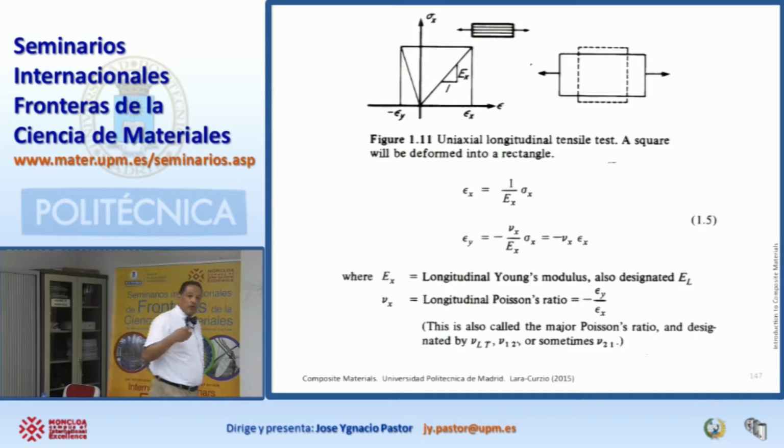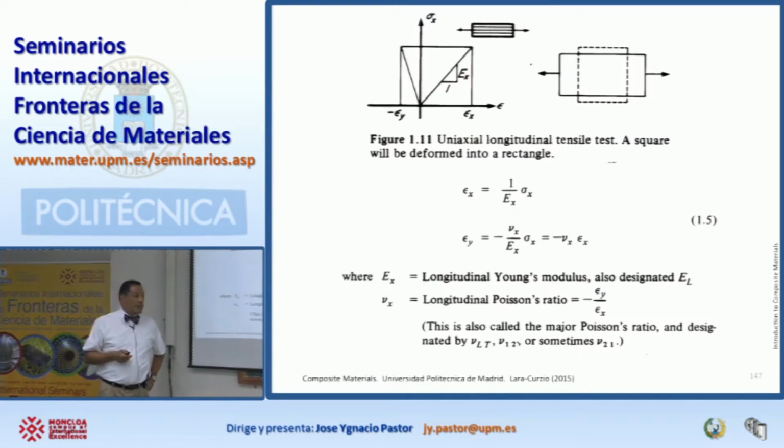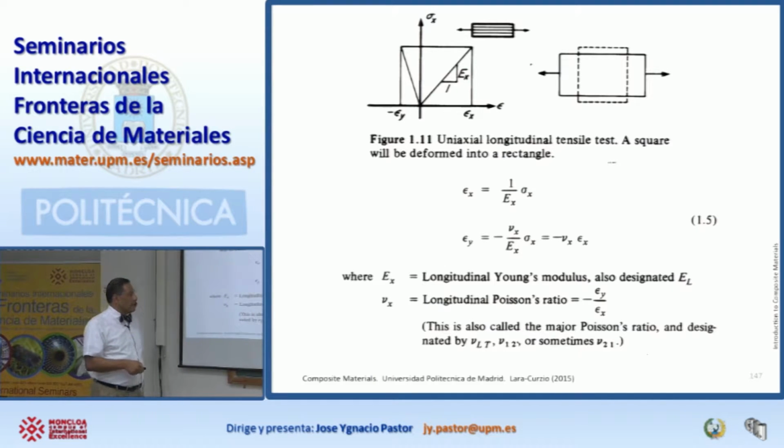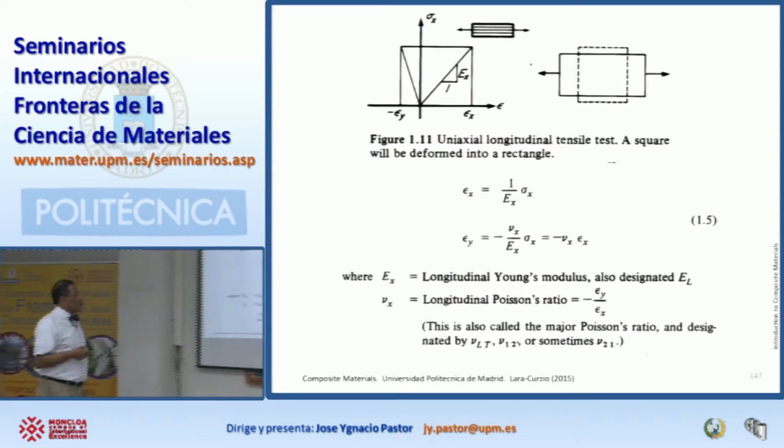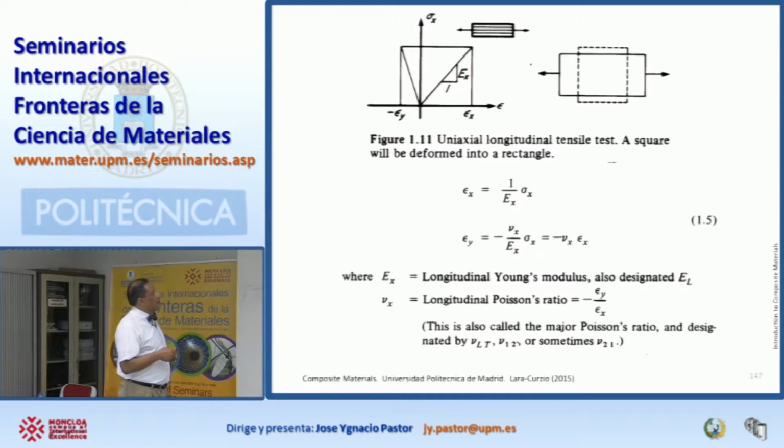Now, if you're an engineer working for Boeing, you are not going to use this type of data. You're only going to design up to the elastic limit, okay? Now, the material may take stresses beyond yield, and that's good. But when you design these things, you don't want them to deform permanently. So all the analysis that you do is going to be based on an elastic analysis. And this is why we only pay attention to the linear portion of the stress-strain curve where the material behaves in an elastic way, okay?